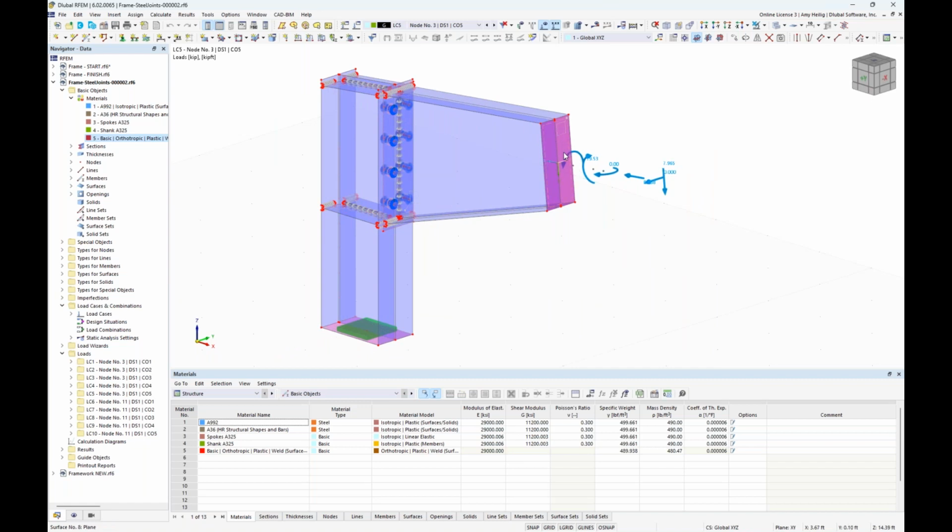This rigid plate allows the load distribution across the entire face, so we don't have to worry about topics like singularities because this load is distributed again to the entire face of these elements. And remember too, that we had to set at least one supported member. Well, we can see that support applied here at the bottom of the column. Okay, so that will cover just the submodel.